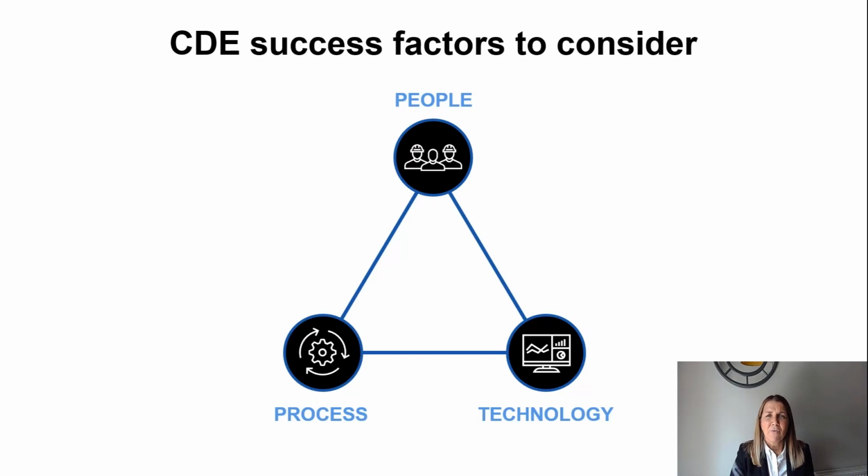A critical component of the CDE is process, or workflows, and the reason common data environments are so imperative to any project or asset. Getting the process right and the stakeholder agreement on a project is essential to getting the CDE right. The key elements of the CDE process are as follows. We assign metadata to each information container, or file, facilitating the management of the process. The metadata defines where the container is situated within its state transition in the review and approval process.